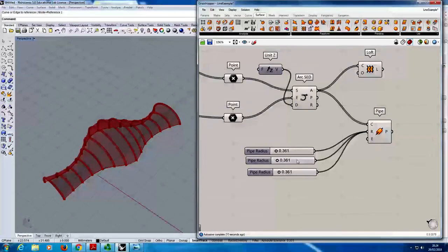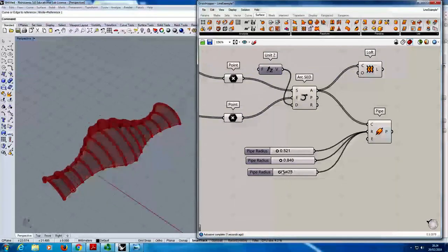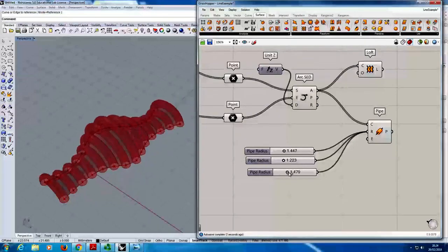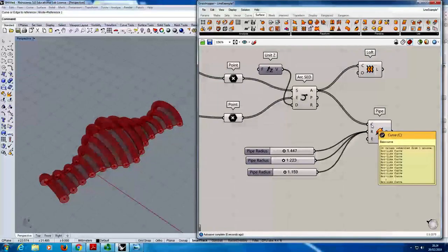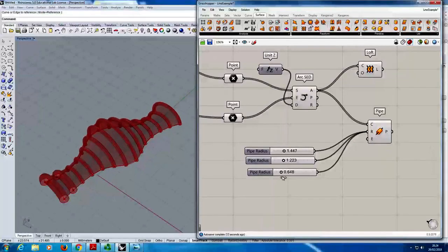And what it will essentially do is assemble that into a list of data there, to which data matching rules will apply. So here I've got 3 sliders, and now I can control these reasonably independently. So I can control at least the first 2 arcs independently. And then, because those data matching rules are applied, I've only got 3 values here, but I've got lots of different values coming in there, so it's just reusing this last value for all of those ones.